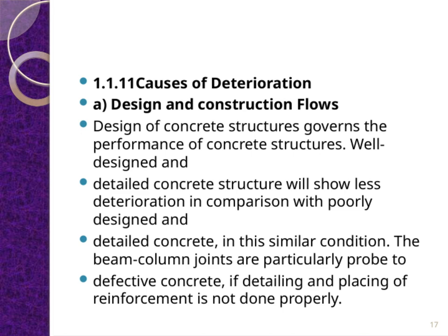One area to pay close attention to is the beam column joints. These joints are particularly vulnerable to defects, especially if the reinforcement isn't placed or detailed properly. Poor detailing and placement can lead to issues that accelerate deterioration, so thorough design and meticulous construction practices are essential to ensure longevity and durability. This connects back to the overall theme, emphasizing that good design isn't just about aesthetics or initial strength. It's about ensuring the structure can withstand the test of time with minimal deterioration.